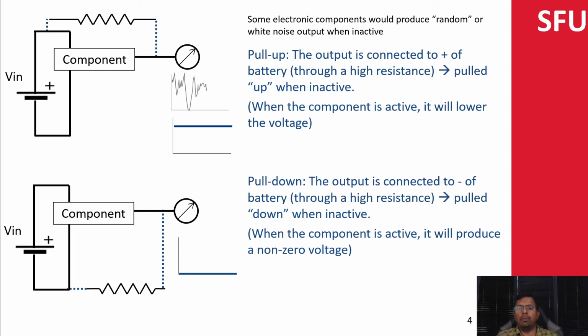So this is how you would use a pull up or a pull down resistance, and you don't have to worry too much about it. Typically, information would be given to you, or whoever is making this sensor or component will tell you that you need to use a particular pull up or pull down resistance. Occasionally they might give you a current range, or based on the voltage and current requirement, you might need to calculate the value of the resistance. More often than not, they will even give the range of the resistance, say just connect a 10 mega ohm resistance, and then there might be some occasional downstream calculation you would need based on the current you consume. There might be some small errors that you need to correct for in your circuit design.